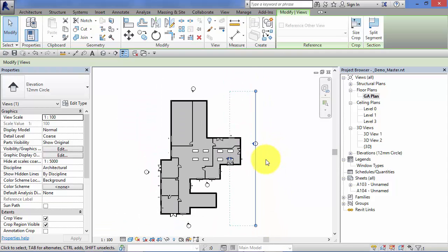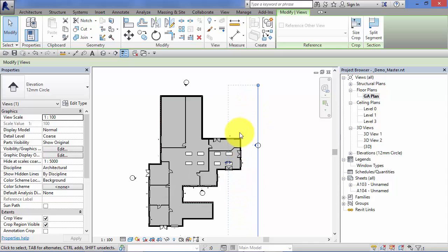now notice how Revit has automatically determined the width of the model, so it's suggesting that you might be interested in an elevation for the whole length of the building. Just watch out for the depth of the elevation, the clip here.